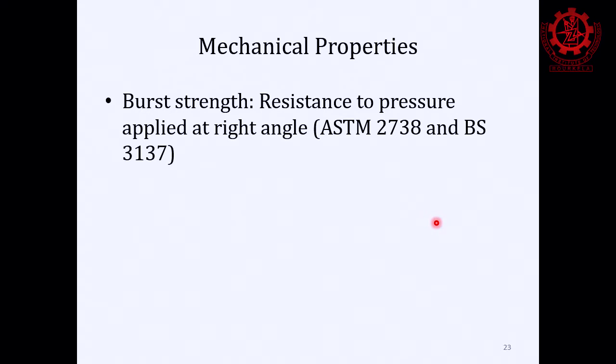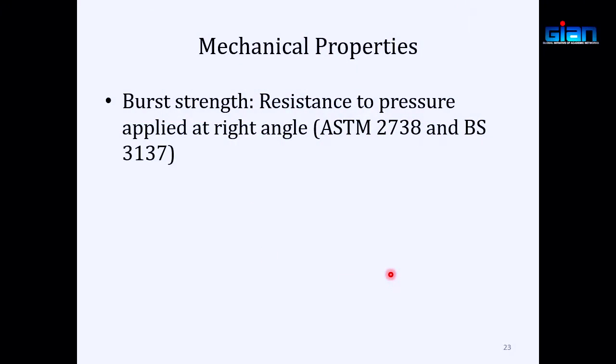As I was mentioning in one of the previous classes, whenever you do this property measurement, like the composition measurement in food analysis where you have AOAC standard protocols, in a similar manner, for many of these mechanical properties of polymeric materials you have a code that specifies the sample size, how much force you will apply, how you will apply it, and how you will measure the elongation or change in length.